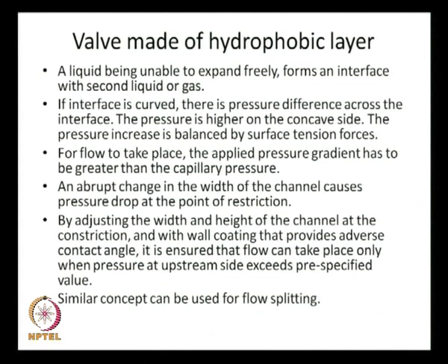Then this other idea that is there, valve made of hydrophobic layer. It is basically something like this: a liquid being unable to expand freely forms an interface with second liquid or gas. That is basically the essence of surface tension. If the interface is curved, there is pressure difference across the interface. The pressure is higher on the concave side and the pressure increase is balanced by surface tension forces.